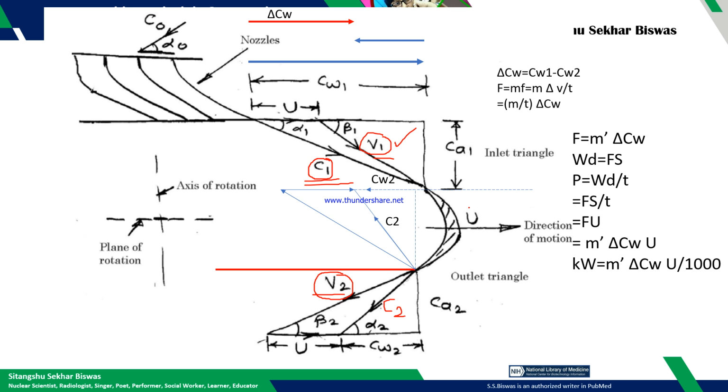So the calculation we did earlier considered purely the impulsive effect, for an impulse turbine. But there are several advantages and disadvantages of both reaction and impulse turbines, so it is better to consider both effects. That's why practical steam turbines are impulse reaction turbines.